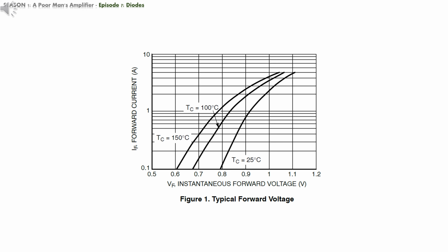Now, after all this run through the electrical characteristics section of the datasheet, we still do not know what the voltage drop across the diode is at 20 milliamperes of current running through the circuit. There is another section of the datasheet that might give us some information about our query. We will now take a look at the typical forward voltage graph.